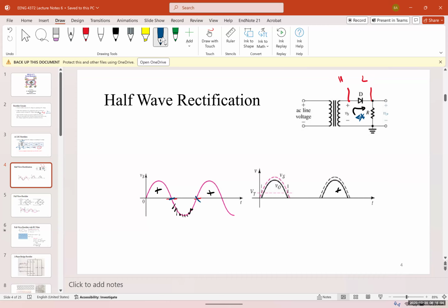It's not like it's going to exactly cut in half, and there are a couple of reasons. Number one, for the diode to be in forward bias, you need a 0.7 volt voltage. So the diode will not even turn on until the voltage is 0.7 volts. And when it turns on, there's a difference between the input voltage and the output voltage, again 0.7 volts. Why? Because the forward voltage bias of a silicon diode is 0.7 volts, meaning it needs 0.7 volts to turn on. And that is a drop that you see in the forward direction.